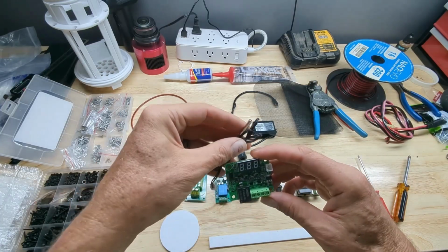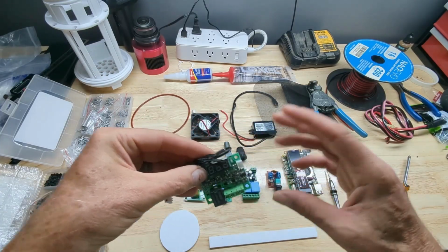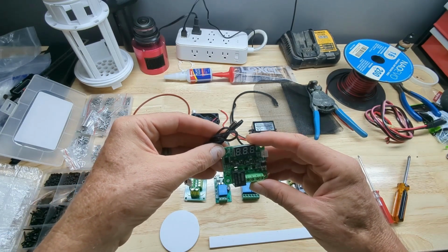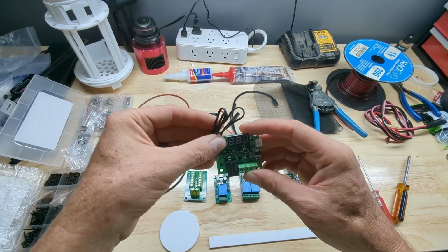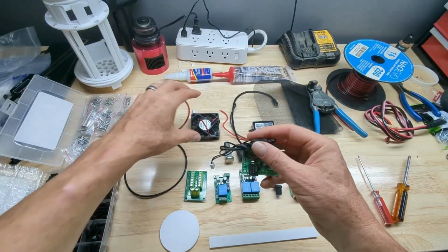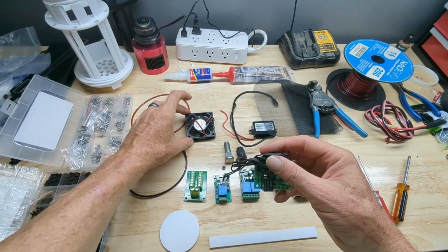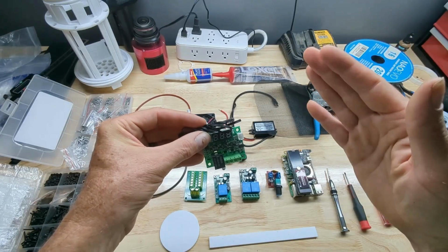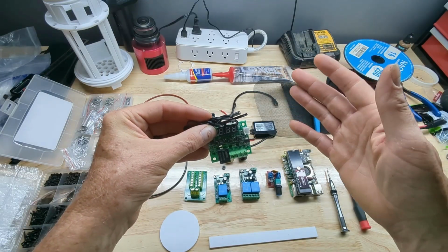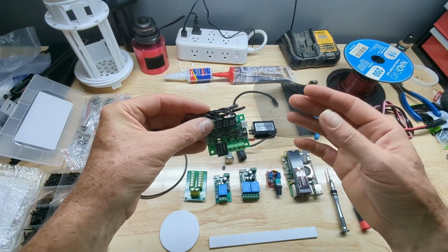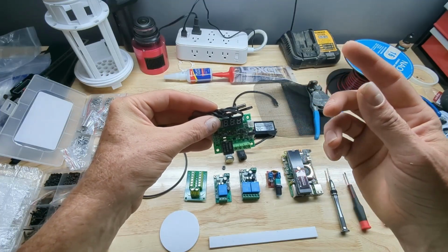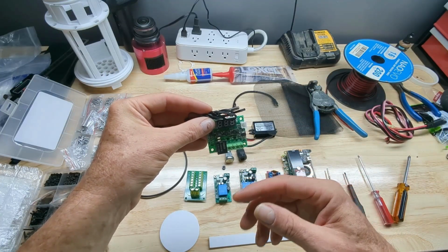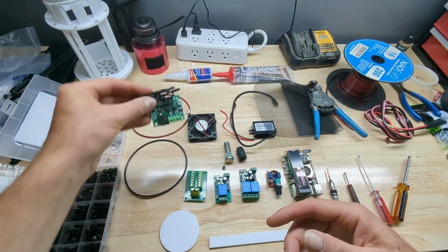So with this, during the daytime, even though everything is off, I still like to keep the enclosure cool. So if it gets above 100 degrees, this little thermostat kicks on and turns our fan on. This little fan that we have here will turn on. Say we have the threshold set at 100 degrees or 110, it'll stay on until it gets all the way back down to 95 degrees, and then it shuts off. And it just repeats that process all day long.